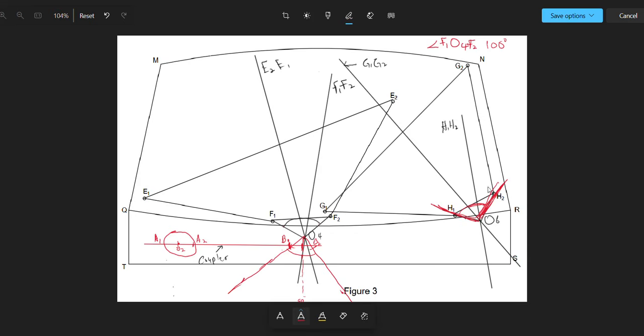When you measure this angle, let's say I got 70 degrees. So you're going to measure this angle and then you divide it by 2. You're going to get 35. And then you draw a vertical line. And then you place your protractor on it in this way, and ensure that this vertical line is in line with the 90-degree mark. You measure 35.